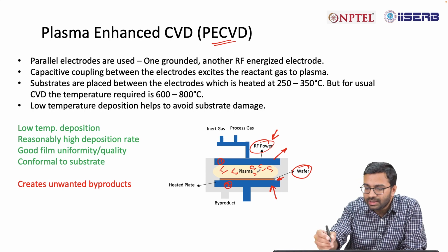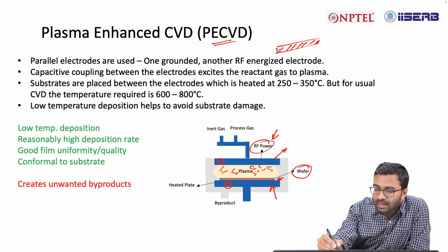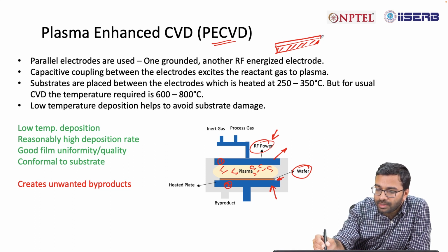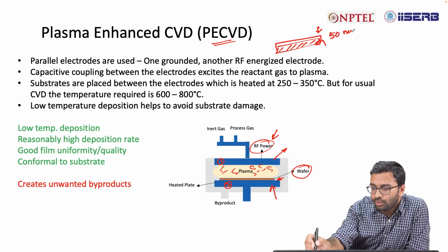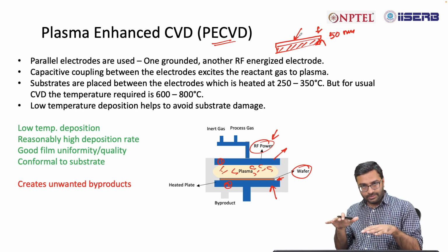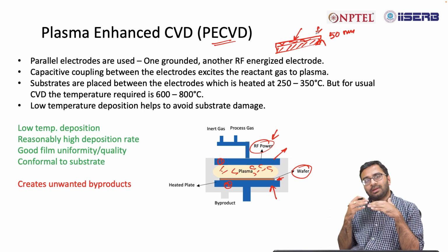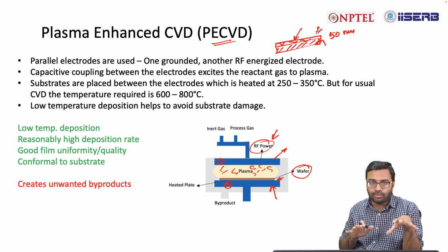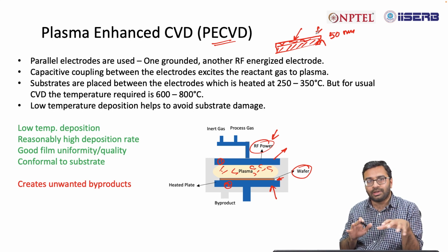What I mean by the quality is, for example, if you have a substrate, say this is the substrate, and you want to deposit, say, one material on top of that, say the width of this deposited material is 15 nanometer. So, a good quality film will show a smooth surface, no defects. There will be fewer defects. I mean, there will be no such defects, and the thickness will be uniform throughout. So, the uniformity also will be great in case of a good quality film.